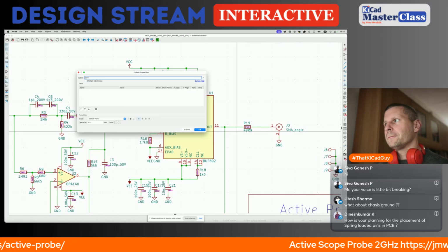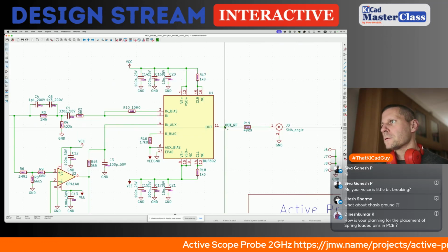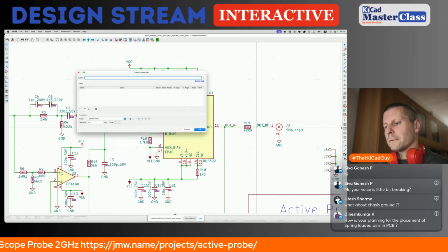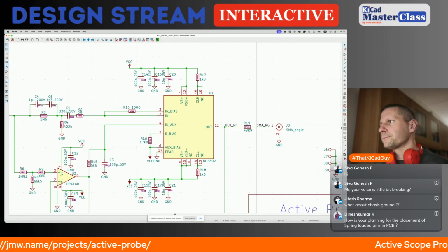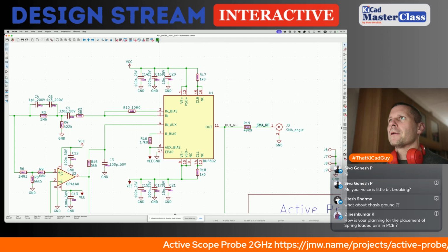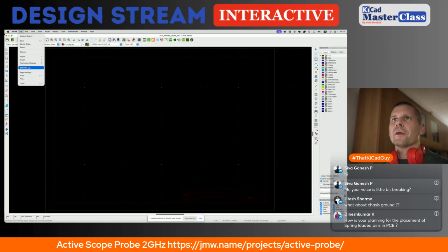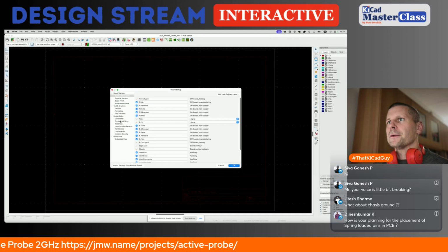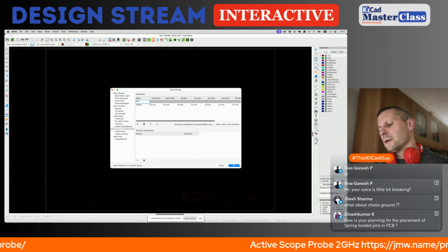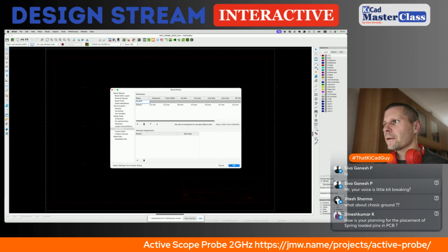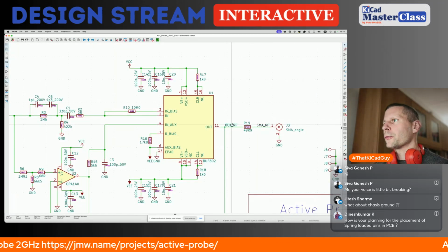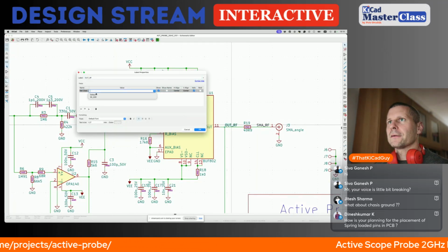So out RF and SMA RF. All RF. Okay. Now I will create the net class for the 50 ohm single-ended. No numbers needed for now. I only want to assign the net class here.